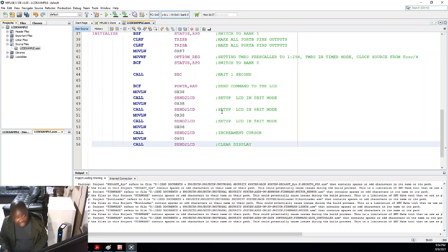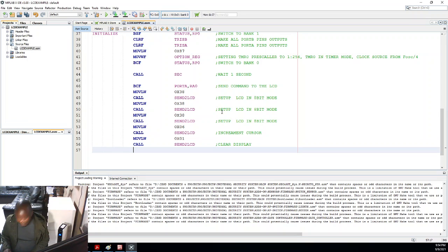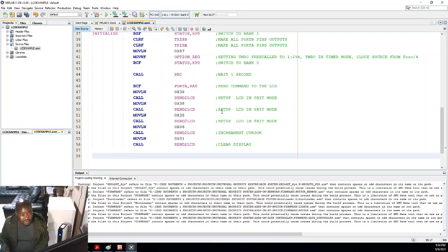Clear your display, right? Now, let's start writing to your LCD. In the main program, I will start by saying, let's jump to the first address. We are already there because every time you clear your LCD, you actually on default jump into that address. But let's jump to that address. The address of the first line and first character on the LCD is address 80.